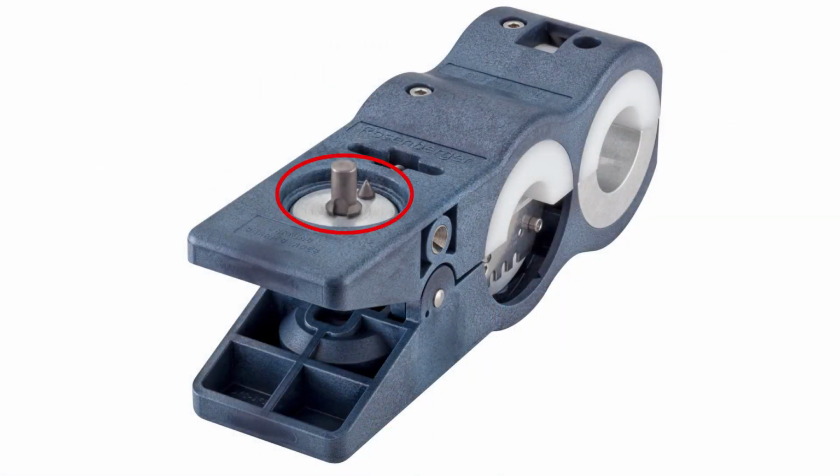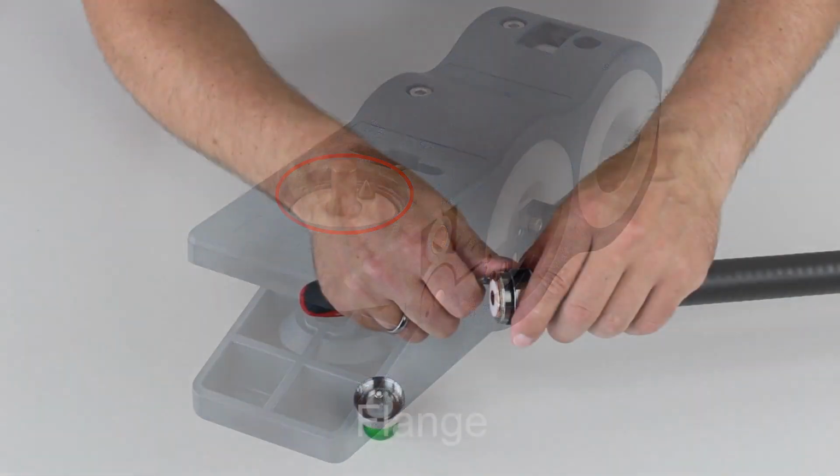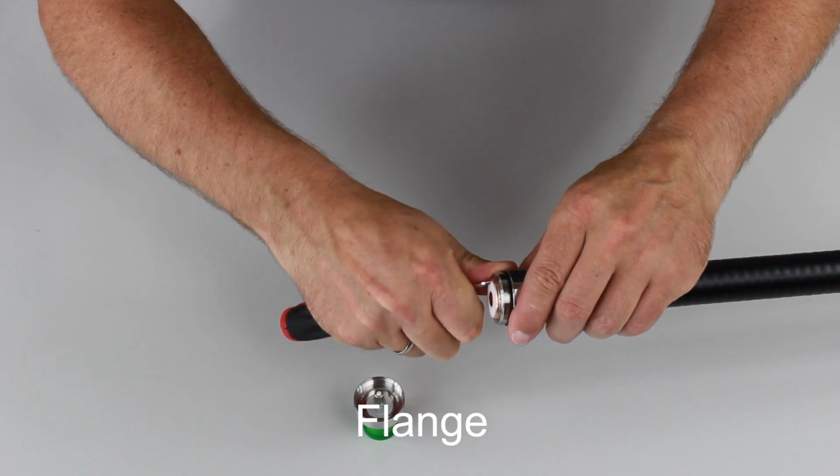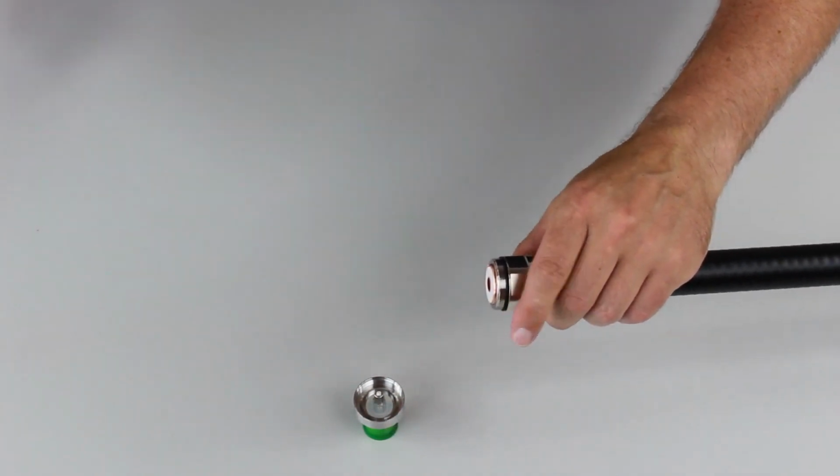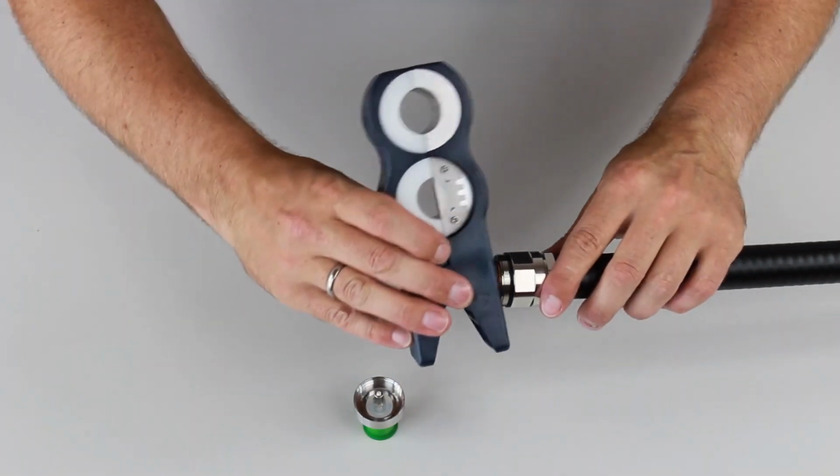Use the marked device on the Uni-Prep tool to flange the outer cable conductor. In order to obtain a good base for the flanging tool, create a free space between the dielectric and copper outer conductor beforehand. Widen the entire copper outer conductor.